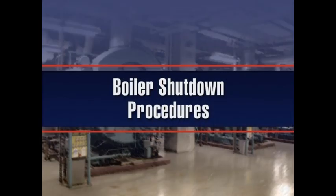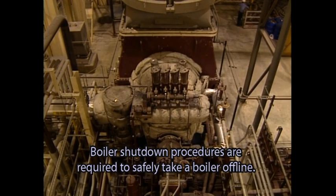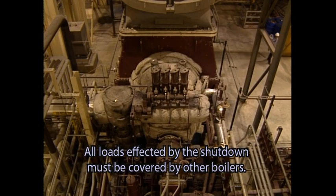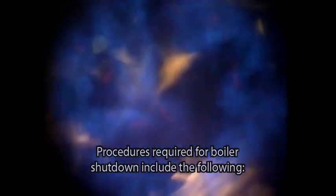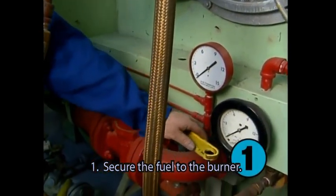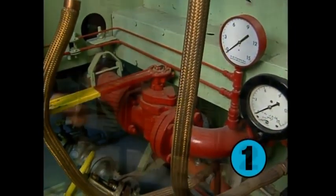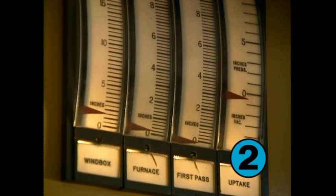Boiler shutdown procedures. Boiler shutdown procedures are required to safely take a boiler offline. All loads affected by the shutdown must be covered by other boilers. Procedures required for boiler shutdown include the following. 1. Secure the fuel to the burner. 2. Reduce the draft to the furnace to allow slow cooling of the furnace.